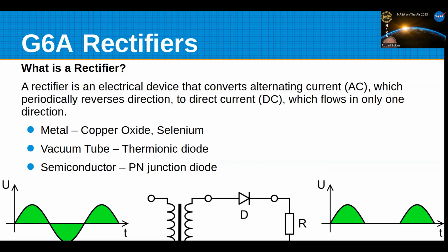But you should know a little bit about rectifiers, particularly in power supplies. This is showing a simple single diode or rectifier power supply. So we're only conducting on half of the cycle. So we're getting a pulsating DC signal out that will then filter and kind of smooth that out to some DC voltage much lower than that.